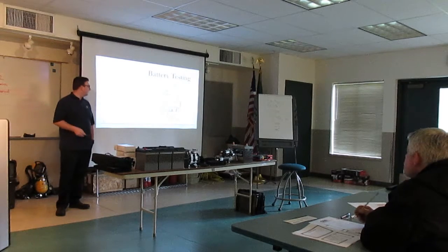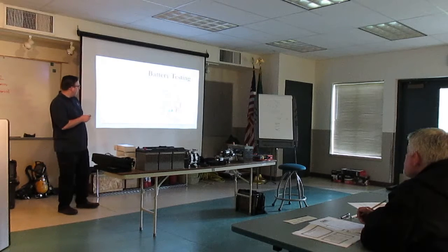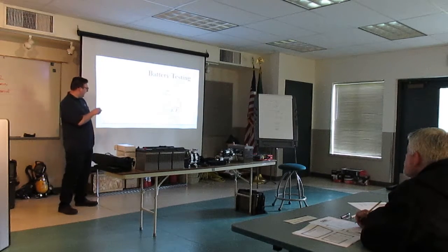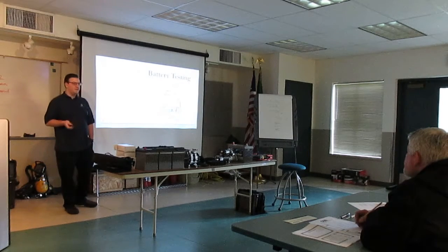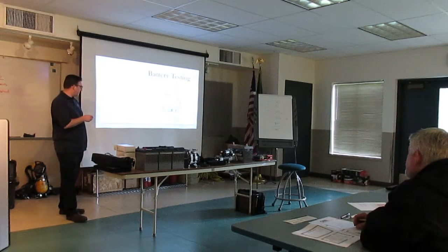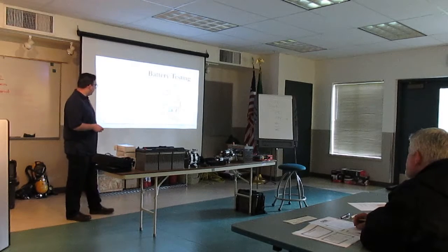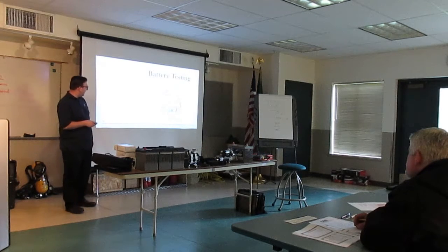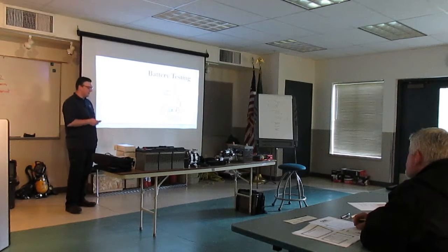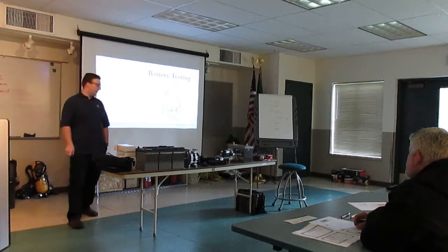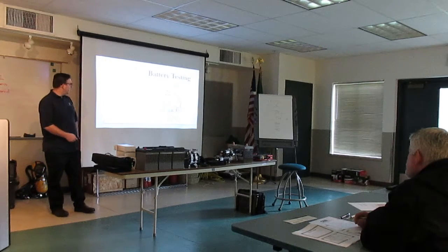Then for battery testing, we have our load tester. About half the battery's cold cranking amps. Here are our minimum load test voltages at different ambient temperatures that you're going to see. So temperature, when you're taking those tests and readings, is going to affect it. If you're doing it on a day when it's 30 degrees, your voltage is going to be a little different than on a 70-degree day. And again, here we have our carbon pile tester. This is a copy of a VAT40 kind of tester, putting it in, loading it up. The automatic electrical testers, you just put your readings in, they'll do the math and give you what they say it's going to be doing as you're going through it.